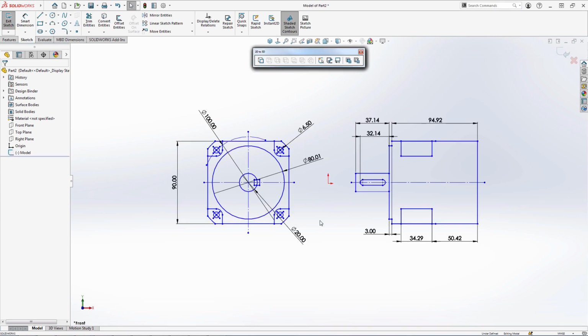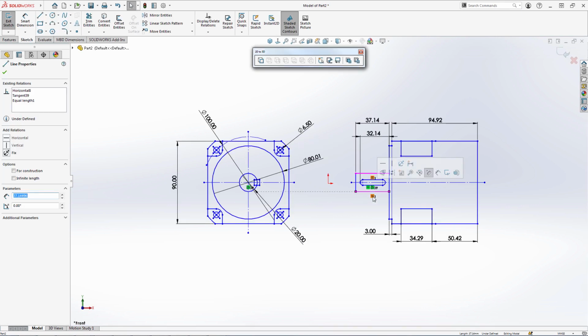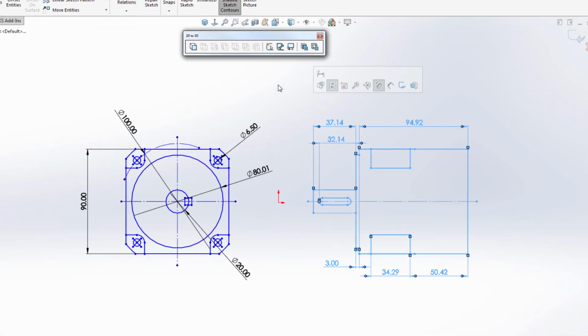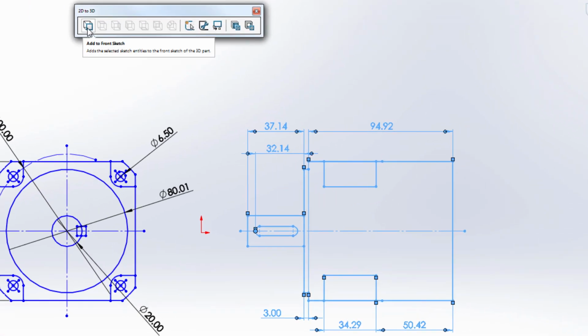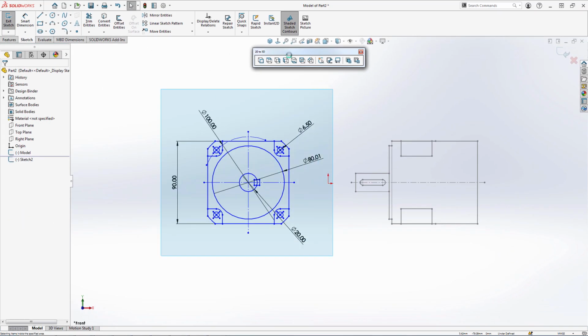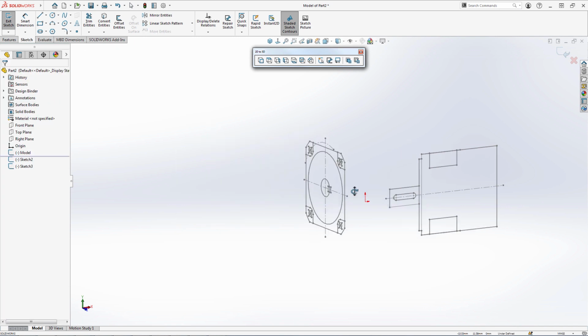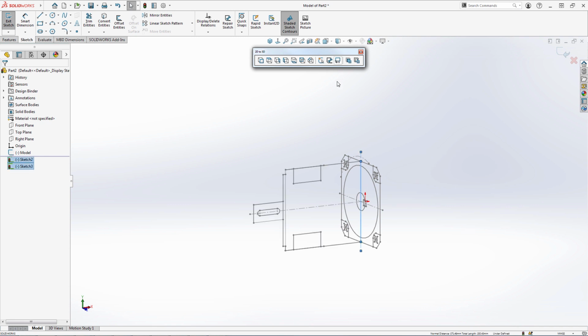Inside the sketch, you will see the dimensions brought through and additional sketch relations which were added. We can window select an area and assign it to be the front. Similarly, we can assign the left view, and SolidWorks rotates the views correctly using a hinged glass box method. Selecting some matching elements, we can then align the views together perfectly.